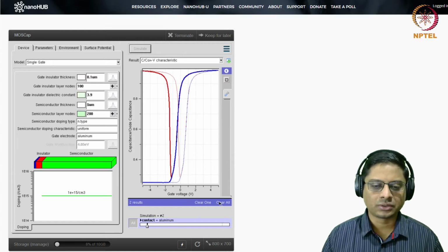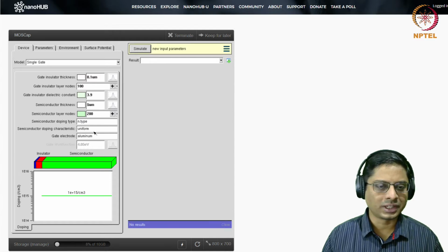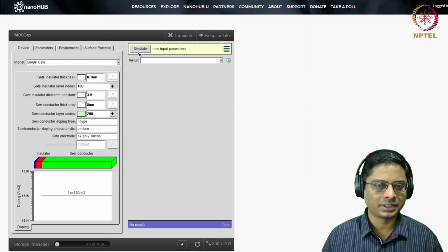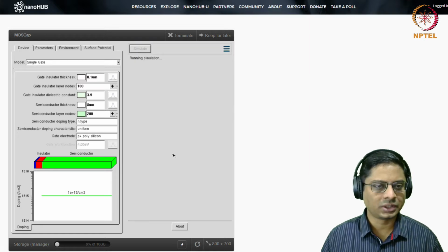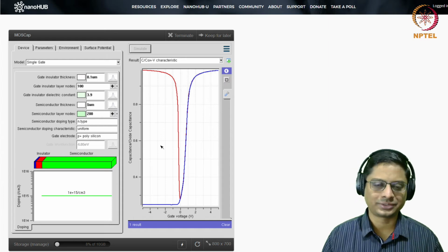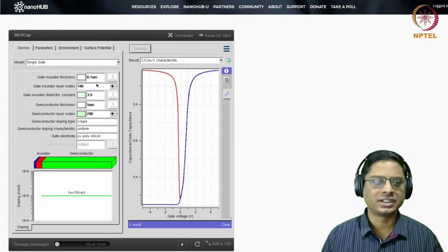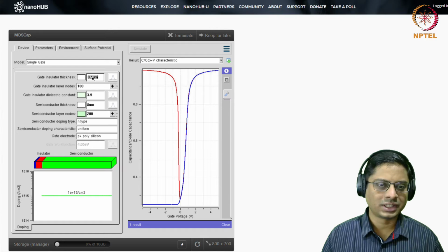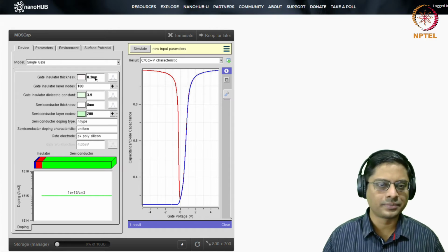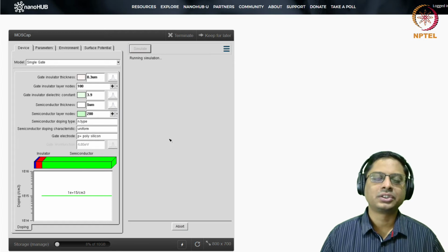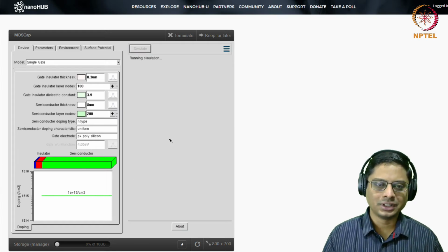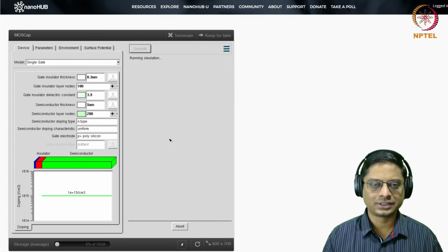All right. So now I'll clear this one again and go back to my P plus poly. Keep it. I'll quickly load the result. Now what happens if I reduce my oxide thickness? We studied that. You could check that out by increasing the oxide thickness and simulating it. So we saw that in inversion, the capacitance was going up, right?